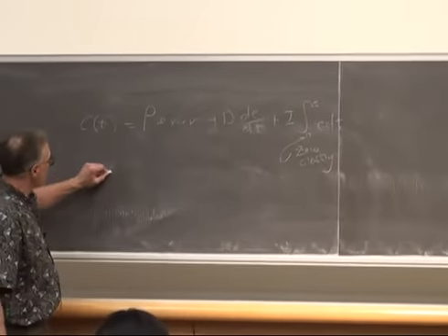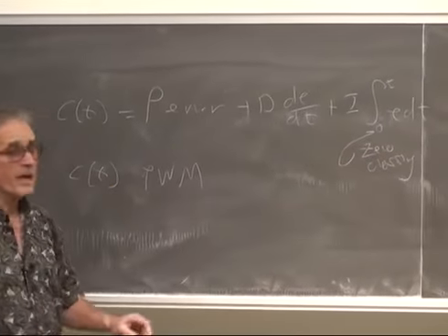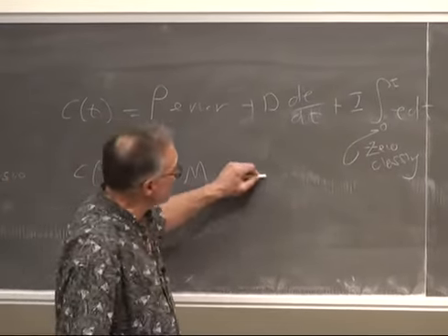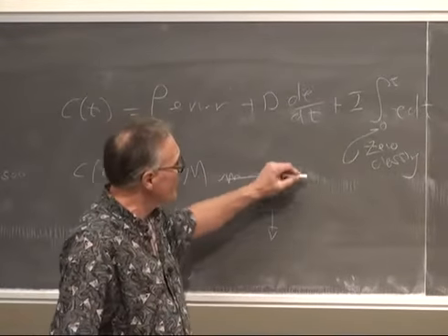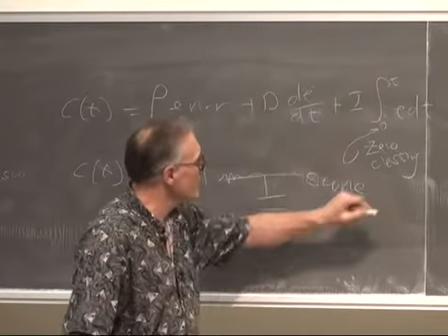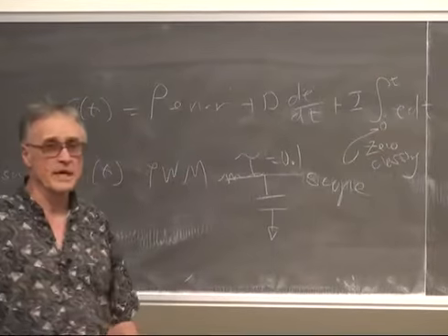Remember that C of t is going to be a PWM signal, and you're going to have to low-pass filter that through about a 1/10 of a second low-pass filter before you go to the scope. So tau of 0.1 second or so.